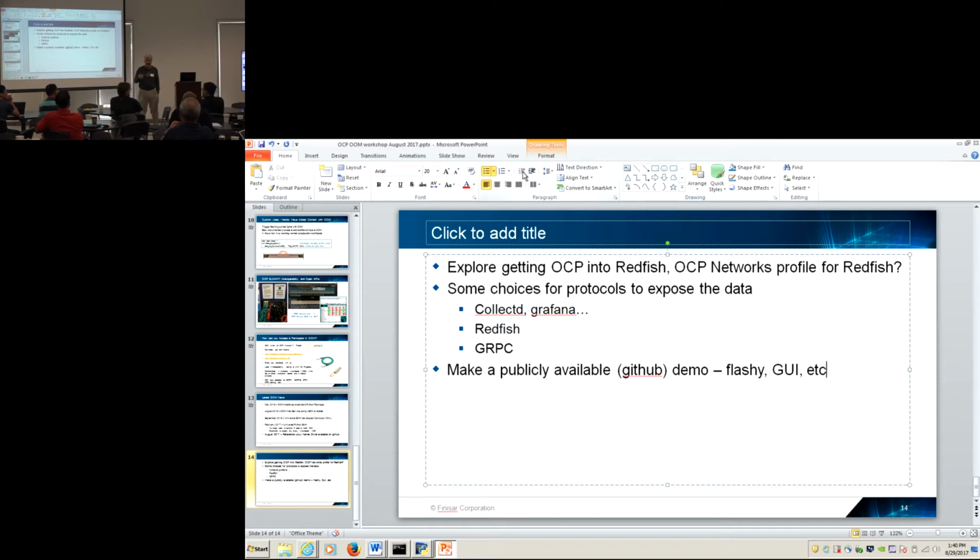Most of the SFP cages have a presence pin, which will generate an interrupt. You can test for presence. Will that generate an interrupt? Most of the switch platforms do, through the CPLD, and then the CPLD waits for changes, which is usually the way it works. Okay. So there is electrically a way to do that. We need to plumb the software.